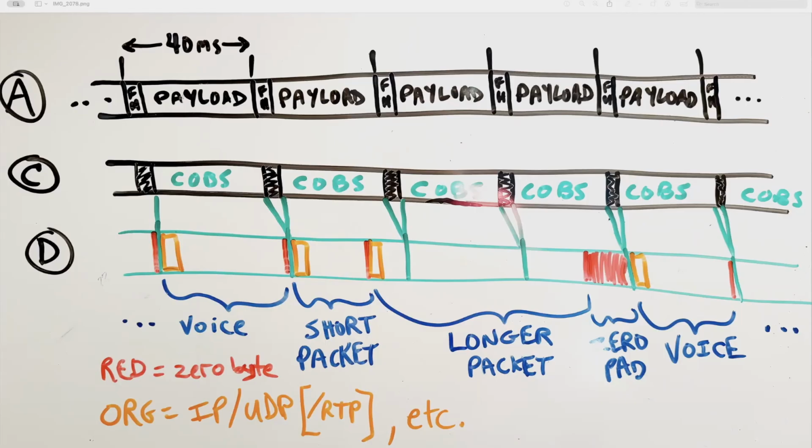If we go ahead and include it, the concern was that we're going to use up a lot of this 3 byte overhead that we have in there. The reason that we have any extra reserved bytes in our custom headers for Opulent Voice is because of hard-won wisdom that you really need to put reserved space in your protocol headers for things that you might want in the future. So if we go ahead and use it up for this, that's less reserved space.